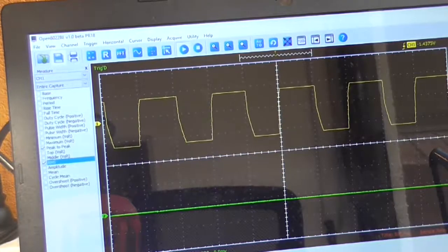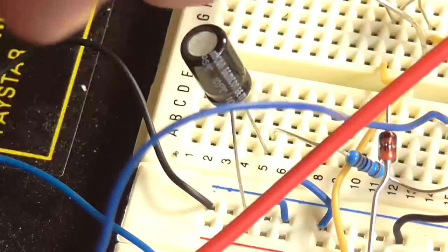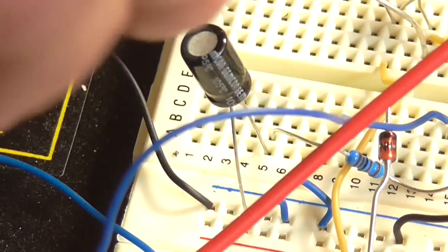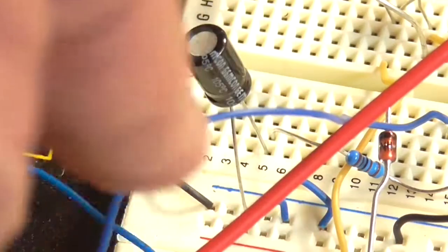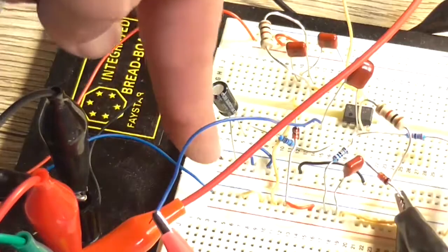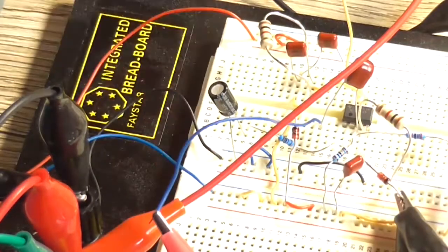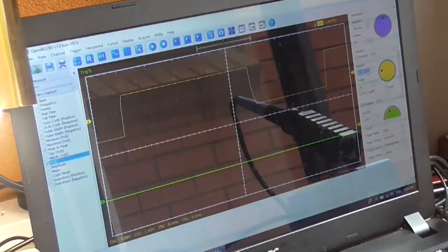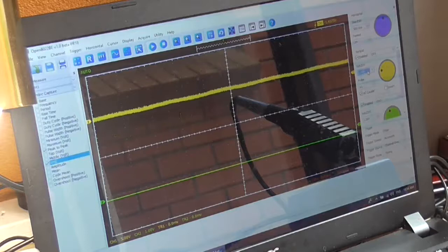It's very square wave. Well, this capacitor here, which is a 10 microfarad non-polar, that's supposed to be going to ground. Currently it's connected to the negative rail. So instead of being there, it should be there. So I've actually connected that capacitor in the wrong place. If I unhook that and connect it to the correct place, what's going to happen to the output waveform? Because basically it's like that capacitor's not even in the circuit.